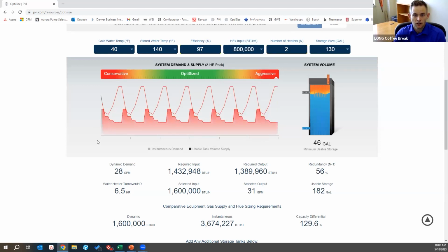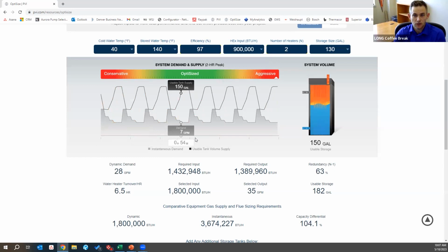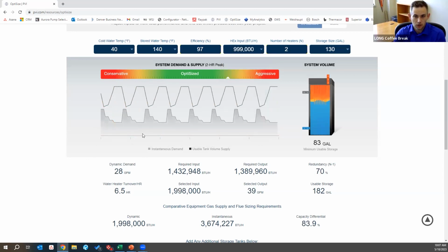So what I'm probably going to do is bump up my input to 800,000 BTUs. Nope, 2 800,000 BTU units are still not going to get it done. So I might just keep going. I'm looking at 2 900,000 BTU units. Oh, it says I'm going to make it, but I'm still really, really aggressive. Okay, maybe let's go to 2 1 million BTU units. Okay, now we're getting a little bit closer, and it looks like we're not going to run out of hot water. So now we look, okay, we've got enough input.